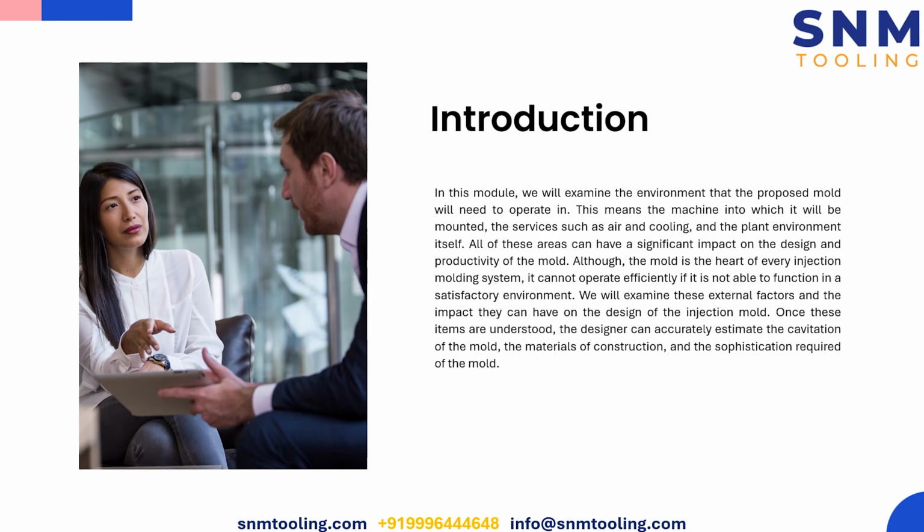Once we know that these factors are to be taken into consideration, they are to be laid down on a checklist to be considered whenever the mold is designed. The designer can then accurately specify or estimate how many cavities are required, and what type of material is required for the mold. Of course, there will be a different material for the mold base and a different material for the inserts. And then what kind of sophistications are required for the mold to have a successful design, and that design must work in practicality.